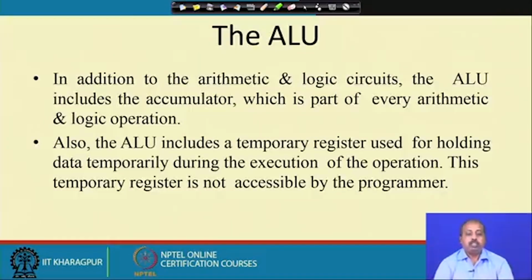The ALU, in addition to arithmetic and logic circuits, includes the accumulator, which is part of every arithmetic and logic operation. I would like to highlight this point. For any ALU operation, the accumulator is taken as one of the operands, the first operand, and the result is also stored in the accumulator. So it is the source operand, the first operand, as well as the destination of these operations.